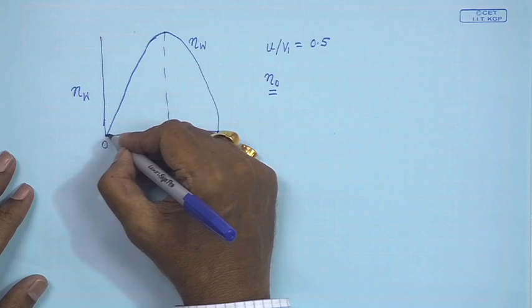And at the same time, when the speed of the machine increases, these frictional losses also increase, so the mechanical efficiency becomes less. Because of these two reasons, the overall efficiency is lower than the wheel efficiency in case of a Pelton wheel. It has also been found, because of this relationship of the speed of the wheel with the mechanical losses, that the maximum of overall efficiency occurs at a value of u by V1 less than 0.5, which can be shown like this.